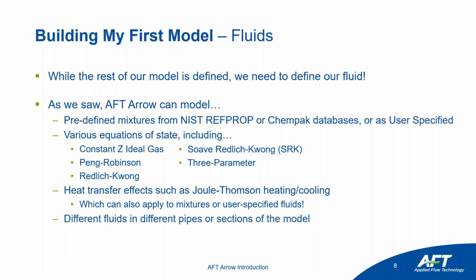One thing I didn't mention is you can also model different fluids in different pipes or different sections of the model. Let's say you're modeling the steam side of a system and then also the process side of the system, you can distinguish those different fluids in those different sections of the model. And then also, as we talked about, you can model dynamic mixing of your different fluids, again, in the example, natural gas mixing with air before feeding to a combustion chamber. Note, however, this has an asterisk, and you will require using either the NIST RefProp database or the ChemPact database for this dynamic mixing capability.